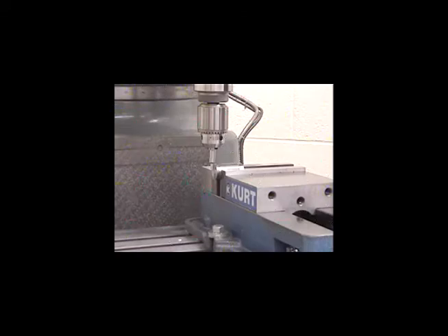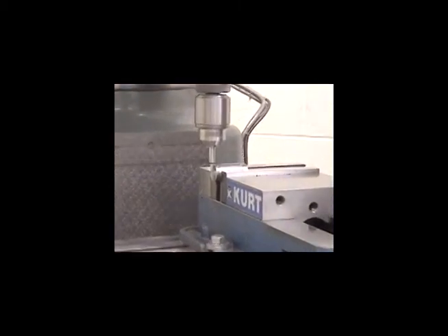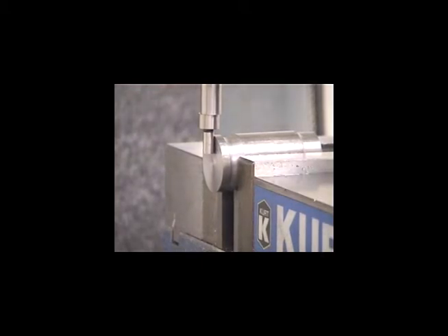Determining the position of the edge of a part is done with an edge finder. Treat edge finders carefully. They are easily damaged by abuse. The edge finder is spun by the mill head, usually in the drill chuck, and the part is moved slowly against the edge finder. The finder will at first quit wobbling, and then at the precise, reproducible location, the edge finder will make a noticeable sideways jog.